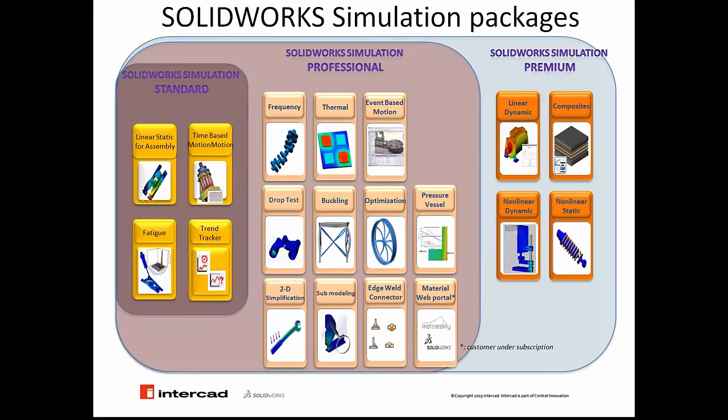All right. Before we go into the case studies, what we would like to highlight is the suite of SolidWorks Simulation, and we understand where we can use the drop test and where we can use the linear or nonlinear dynamic. If you have a look, we're starting with SolidWorks Simulation Standard. We can do linear static on assemblies, components, and parts. We can do time-based motion, fatigue studies, and trend tracker.